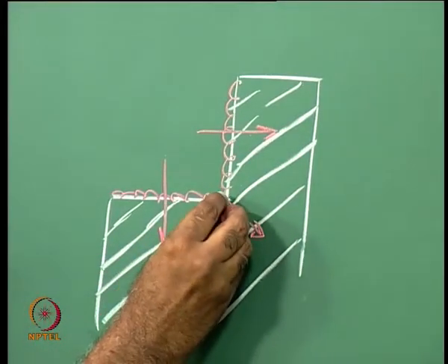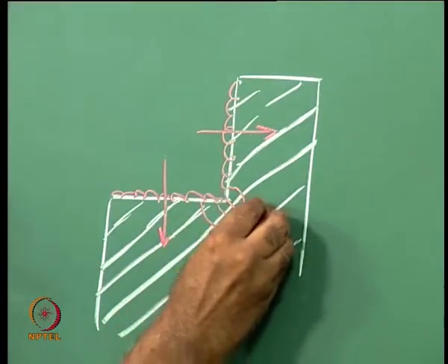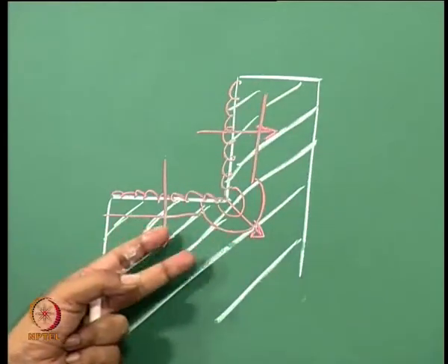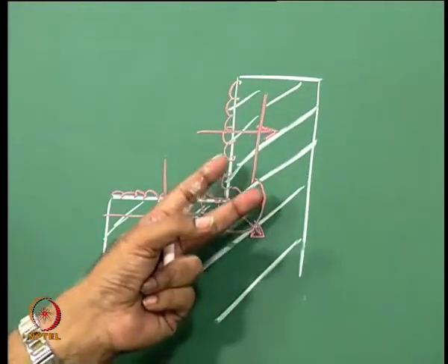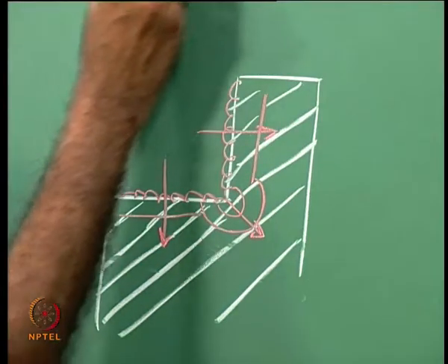In other words, over here, since it is normal to this point, it will go as a circle, and over here it will go as a line. This is how burning takes place, normal to the surface. Maybe we will have to look at this in some detail when we come to different configurations of the propellant grain. Therefore, we tell ourselves, for anything to take place, I define something like a burning